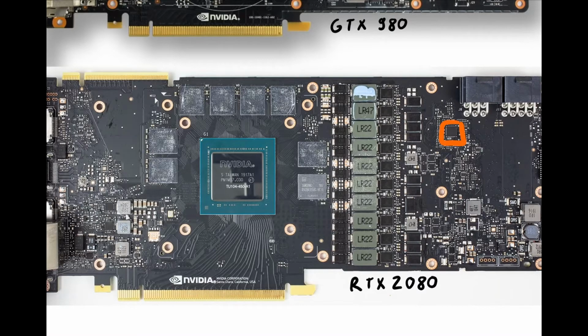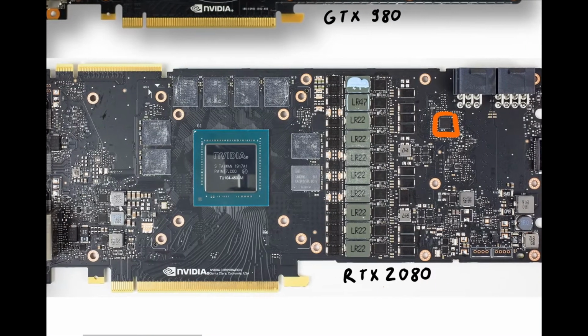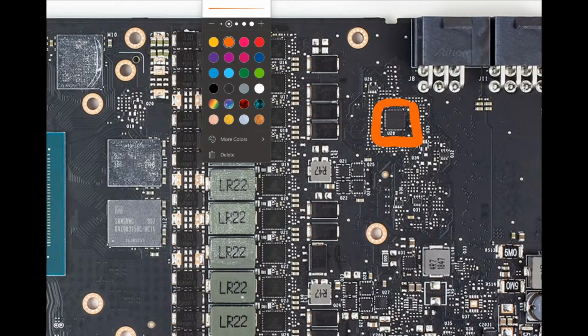PWM controllers are mostly this size. It's not always a guarantee that they are PWM controllers, but if you see a chip this size in this region of the PCB, you can be pretty safe that it's a PWM controller, and if it's not, you will find out when you put in the numbers that are written on it. So you can see it on the photo, but there will be something written like UP.